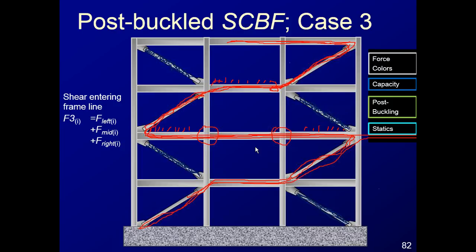Okay. Next question. When designing connections for mechanism forces, do the phi factors apply to the capacity checks? Yes. So when designing members for mechanism forces, the AISC method gives you forces that you're expected to use along with the design strengths that you have from the main specification.